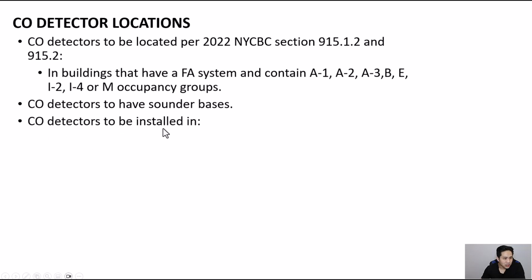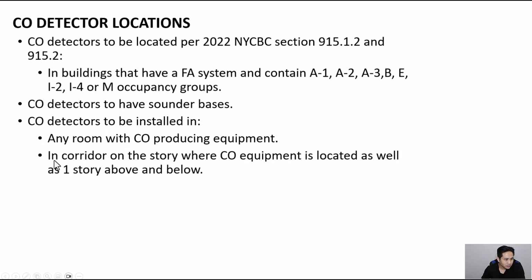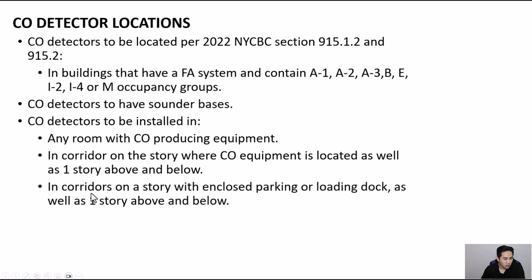CO detectors to be installed in these spaces here: any room with CO producing equipment, in corridors on the story where CO equipment is located, as well as one story above and below, in corridors on a story with enclosed parking or loading dock, as well as one story above and below. Activation of the CO detector shall shut down the source of that carbon monoxide.